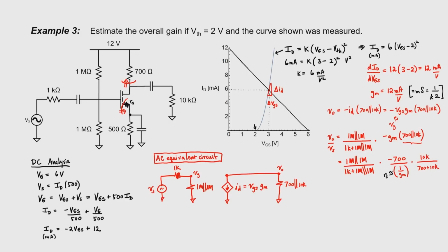That allows us to revise our AC circuit a little bit. So rather than write it the way I have, let's redraw this current source as a voltage source. Let's use just the load resistor over here at the output side and reflect our equation. So the output impedance here is 700 ohms, and that's now properly reflected in our AC equivalent circuit as well. Let's replace our current source with the voltage source. If you like the current source, you can keep it there. These methods are equivalent, but I like voltage sources.